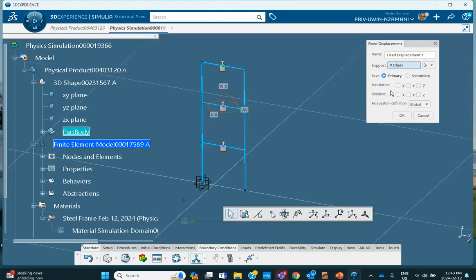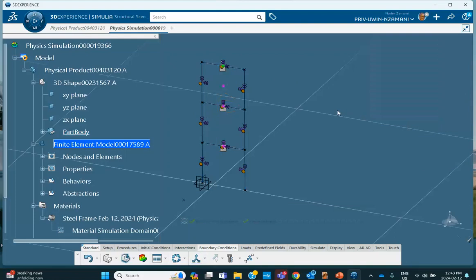Yeah, you cannot move in direction X, and because it's two-dimensional, in principle, we should say rotation about Y and rotation about Z also equal to 0. If you left these out, it's probably okay, but actually, if you leave it out, it can twist, go on the torsional condition. We don't want that.